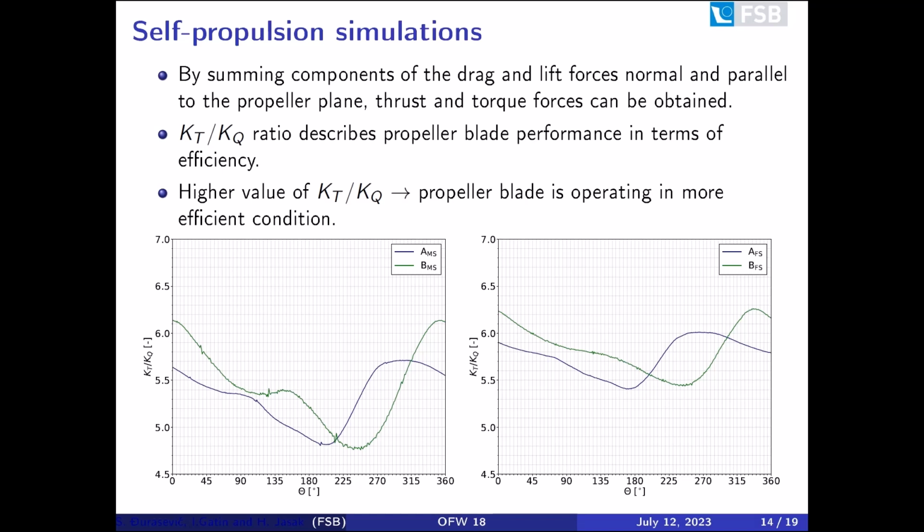Ratio decreases and reaches its minimum at approximately 210 degrees in case of partial propeller rotation representation, and at approximately 250 degrees in case of inertial propeller representation. Minimum occurs in a tangential position where usually values of the inflow axial velocity are lowest and the angles of